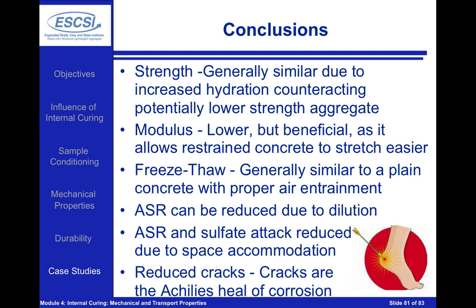air entrainment. We saw that there were some benefits in ASR and sulfate attack, mainly because of dilution effects with ASR, but also both are going to provide a little bit of additional space for expansive products to form, which will reduce some of the stresses in the system.